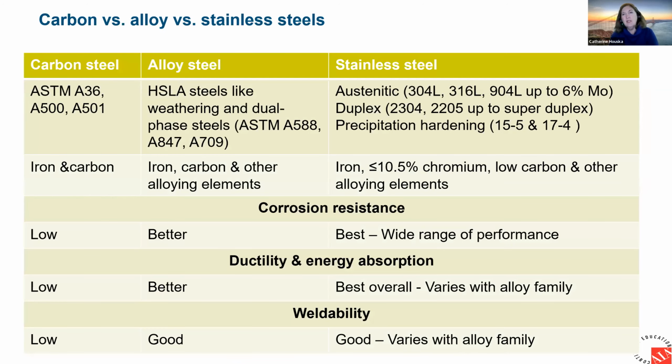It seemed important to start with a basic comparison. Carbon steel, alloy steel, stainless steel, what do you use where? Clearly, if you can use carbon steel, are able to protect it and regularly inspect it to keep it protected, it might be your most cost-effective choice.